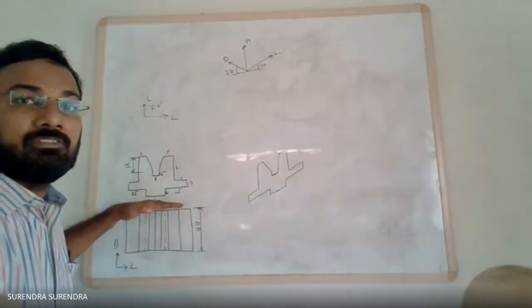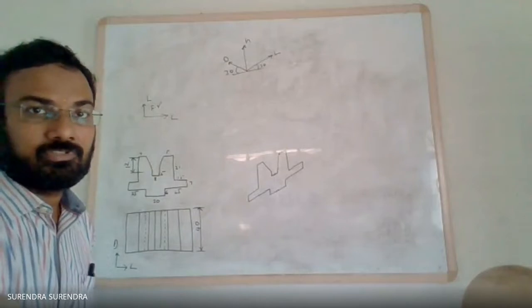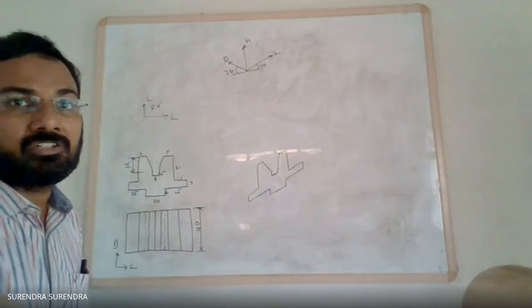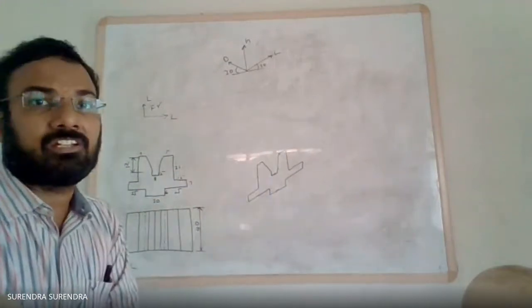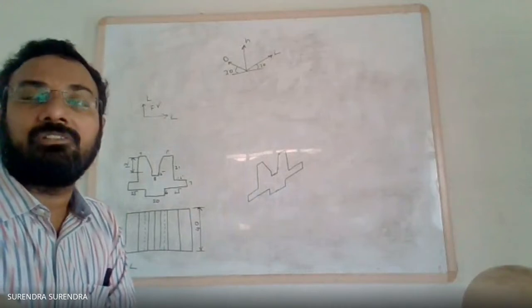Drawing the front view shape in isometric view. In the same shape, the horizontal lines we have tilted to 30 degrees, and the vertical lines we have drawn as they are, vertical.